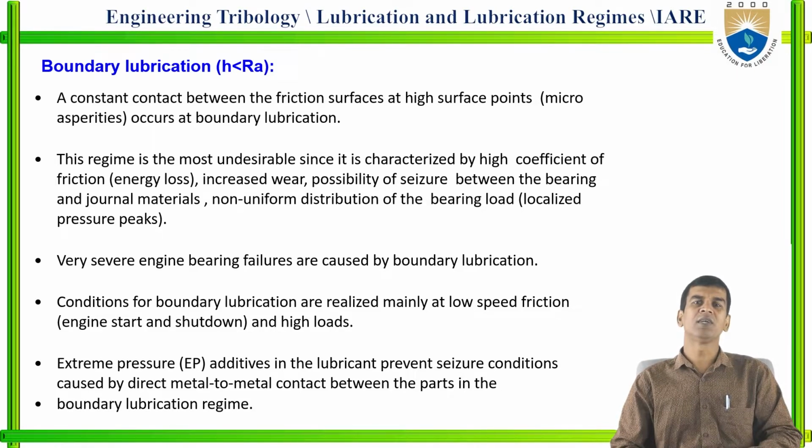Boundary lubrication means contact between the surfaces occurs for a greater amount of time. Because of that, the friction rate will be higher, and when friction is higher, wear also increases. Due to boundary lubrication, there is a possibility of seizure of the metal surfaces.